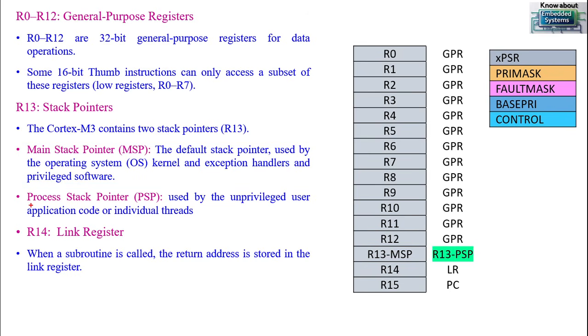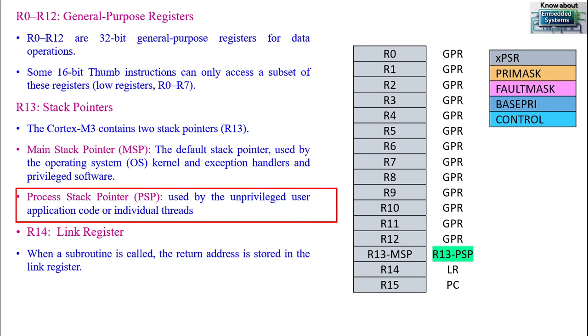And what about the process stack pointer? We have one more stack pointer, PSP. PSP stands for process stack pointer, which is used by unprivileged user applications. Unprivileged is nothing but normal user mode. Whenever you're in normal user mode, this PSP is used. In detail, we'll see later.